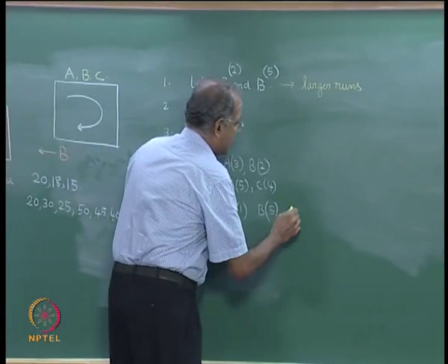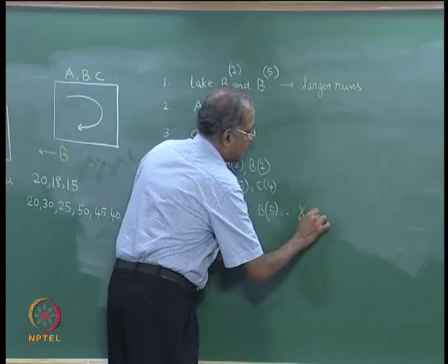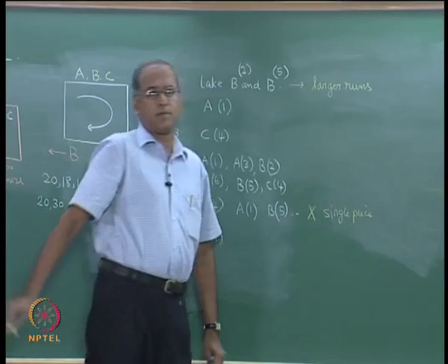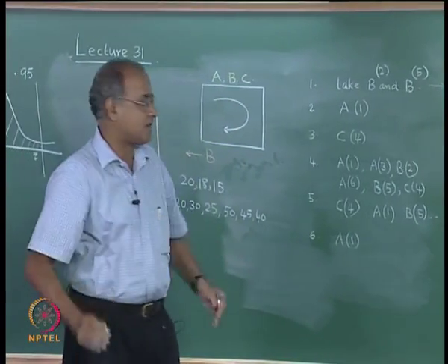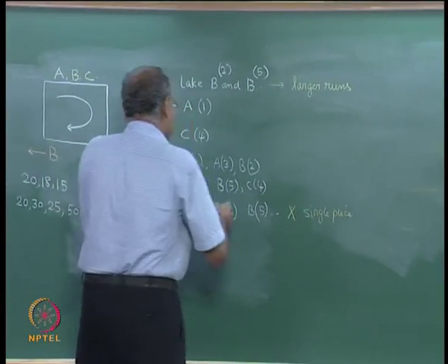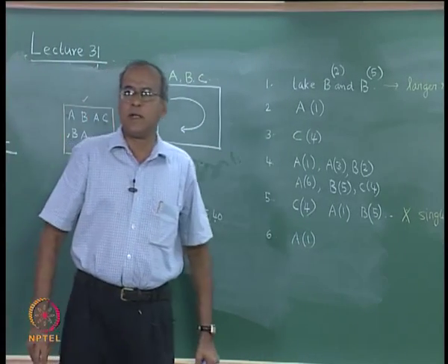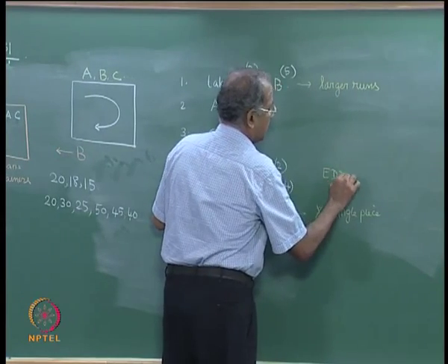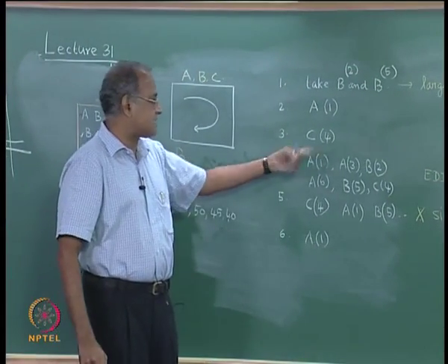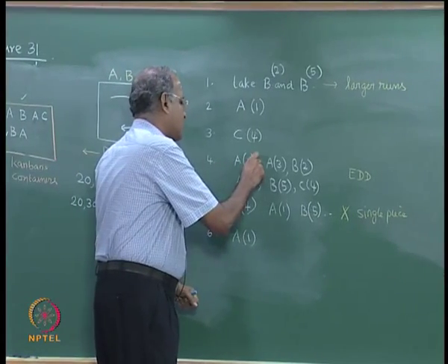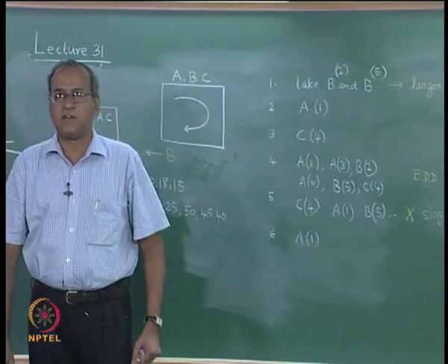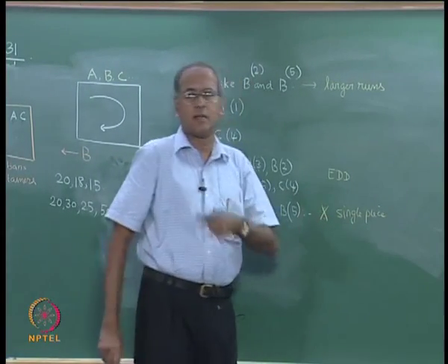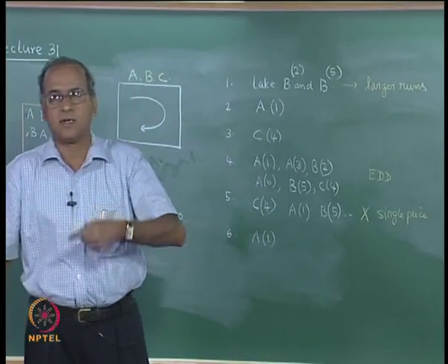Now, in a way cyclic is the best in terms of single piece flow. This will produce items at very short runs. So, cyclic is a very good rule. Sometimes to meet due dates we start looking at earliest due date rules. So, EDD can still give us, as in this case, 2 consecutive containers of A to be processed, which takes us away from the idea of a single piece flow or a short run and so on.